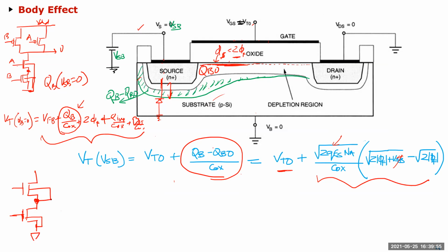But the problem is, this is a big diode here, because that's a diode between the source and bulk and the substrate, and this adds capacitance. We derived the equation just a while before, so this will add that nonlinear capacitor Cj, and this will slow down your devices basically. And that's the main reason why you can't just keep doing it.